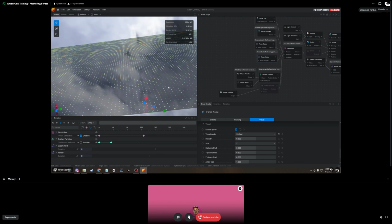And then, remember that particles themselves can be a force as well. So, for instance, with these explosions, we get a lot of these crazy, cool tendrils just solely because we're injecting a lot of force over the life of the particle, which is really awesome. And you can use emitters as forces as well with, say, pressure. For instance, if I don't have pressure at all, we just have this really basic high velocity sim, but you come in and add more pressure, and that's going to give you quite a bit more smoke and fire.